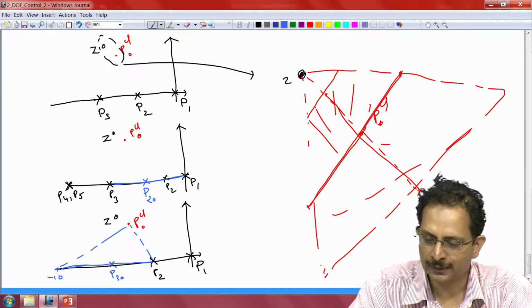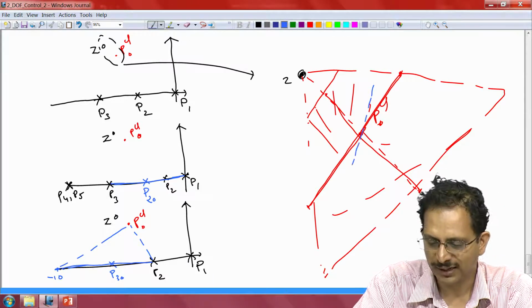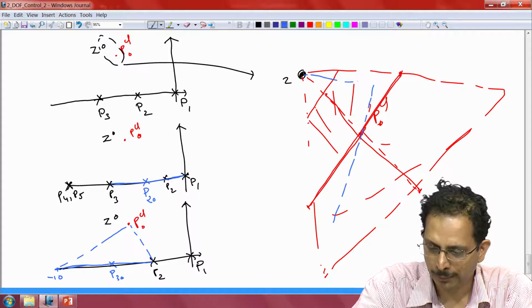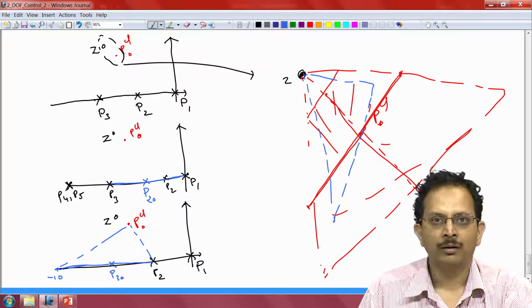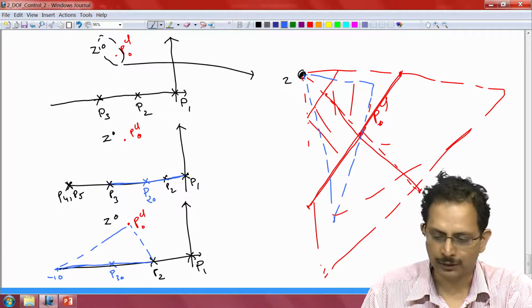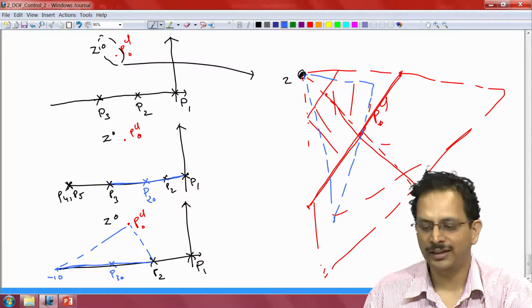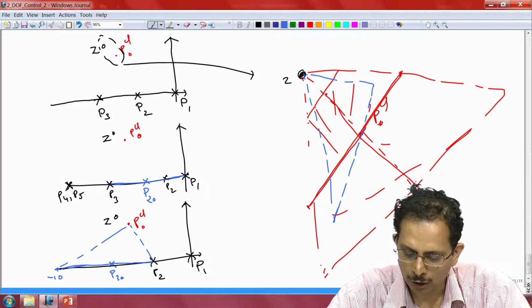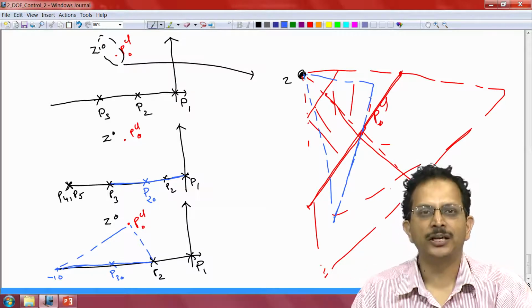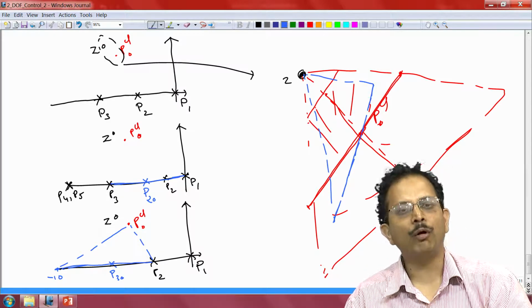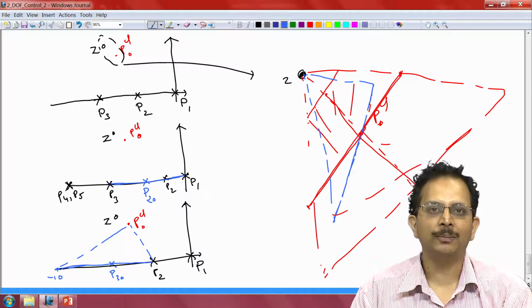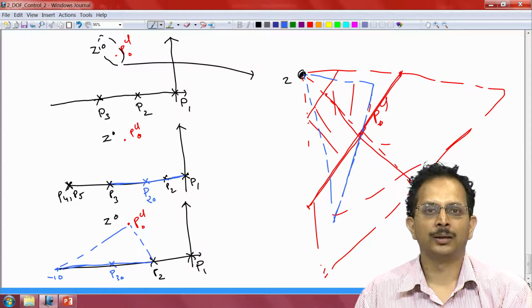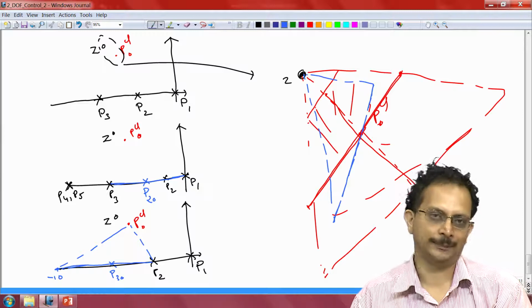So, this triangle would be similar to the triangle described by the point PCL when the pole location P3 were to change within the specified limits. Now, this is the line along which the closed loop pole PCL will vary if there was no uncertainty either in the gain of the plant or in the pole location P2 of the plant.